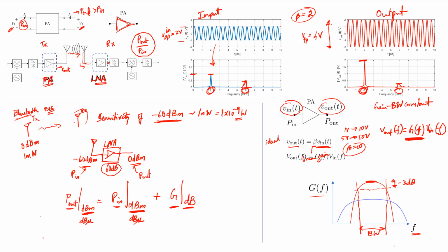So for the red curve, it's going to look like that. And for the blue curve that we see here, we can see that the gain is a lower value than the red curve. And if you see the minus 3 dB point, we clearly see that the 3 dB bandwidth is much wider than that of the red curve, meaning that by compromising the gain, the bandwidth has improved. In other words, if gain goes up, the bandwidth goes down, maintaining the gain bandwidth product to be a constant.